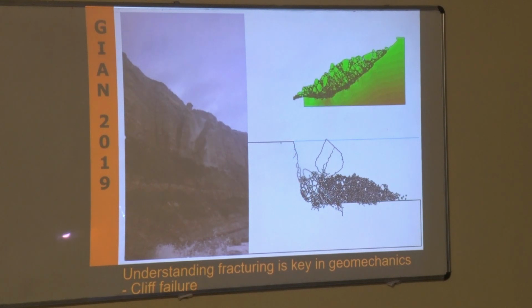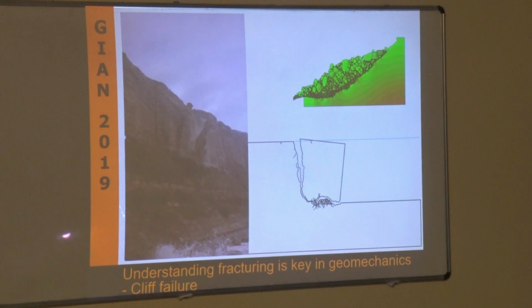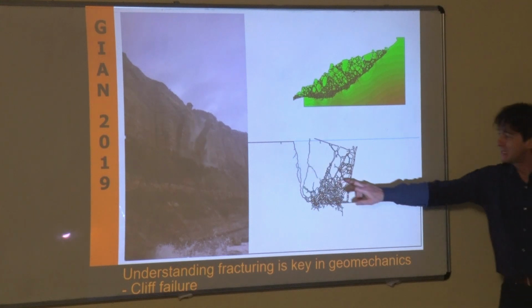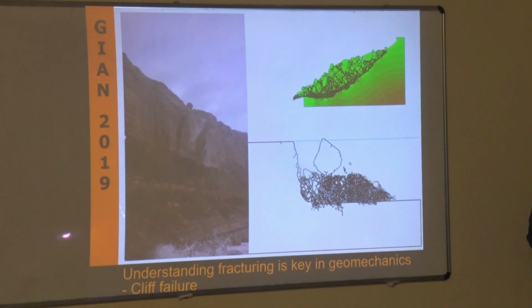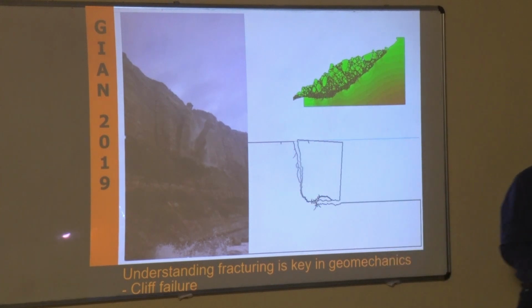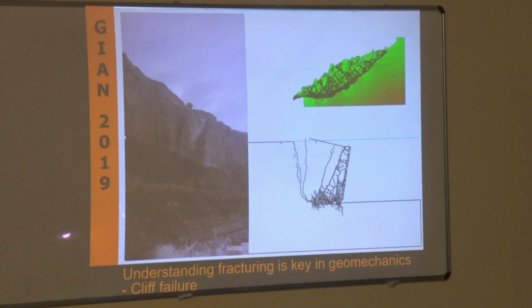And you start reproducing fragmentation, primary fragmentation, failure, secondary fragmentation, flows of material, and so forth. And these are not really easy. But you can see your fracture developing. You can see that your blocks are no longer the same size, but they change as a function of where they are in the process and how far they are, for example, from the surface of failure.